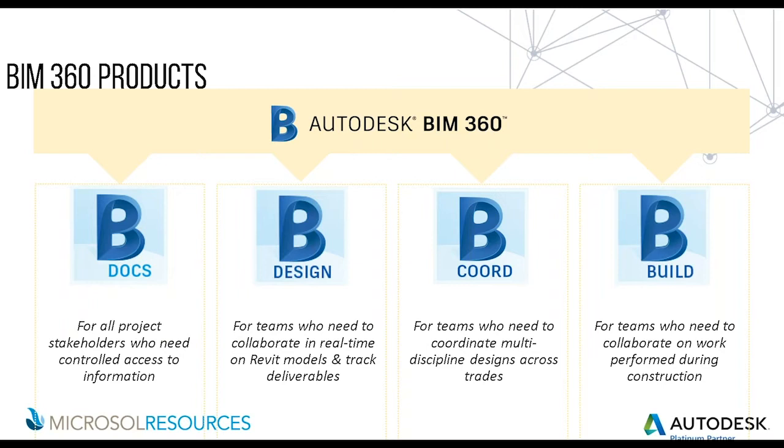Then there is BIM 360 Build, which was previously known as BIM 360 Field. This improves construction quality control and job site safety through the use of checklists. Also with Build, users can create, assign, and manage issues, RFIs, submittals, and track field performance with daily construction reports. All of these packages come with insight tools to project analytics as well as document management capabilities, including file sharing, publishing drawings, versioning, and document comparison.